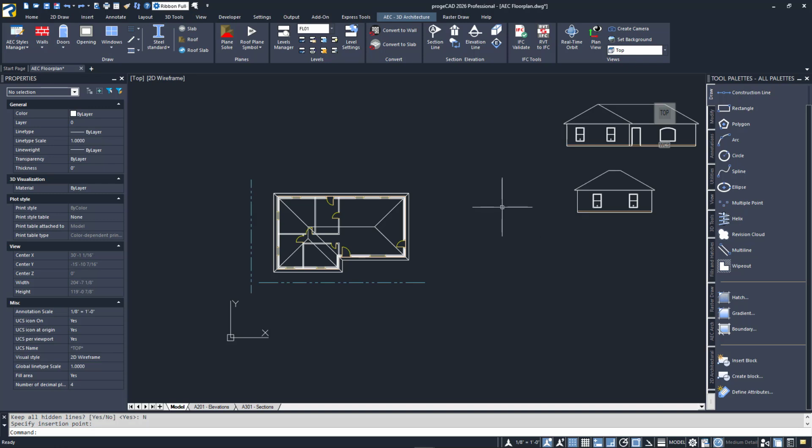It's time to create a couple of section views now. In general, they work the same way. I'll click on the Section View tool, and again, I'm prompted to draw the line. Remembering my lesson from the last elevation, I want to make sure the direction I want is the section to view. Notice this time, instead of ending at the second point, I can choose to continue. We'll do that next, but for this one, I'm done. I'll follow the same workflow to place my new section view.